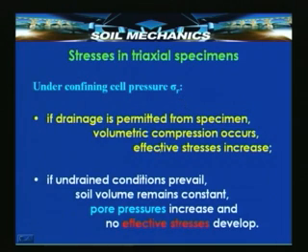Now, this stress condition inside the specimen, which is basically sigma r and sigma a, depends on the drainage conditions. If drainage is permitted from this specimen, then as the water expels out, a volumetric compression takes place in the specimen, and as the water goes out, effective stresses develop in the specimen.